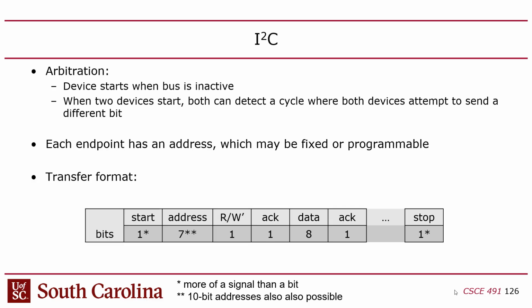I always get the stop is when you change the data when the clock, again, yeah, it's the same idea as you changing the data when the clock is high. But I'll show you the timing diagram after this. It's similar to the start though. It's basically just releasing control. Make sense? Everyone with me? Okay, so that's the premise.